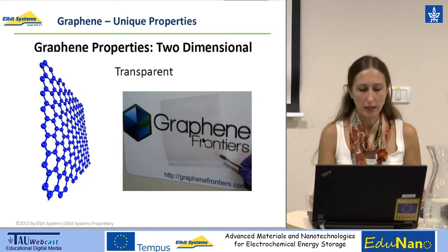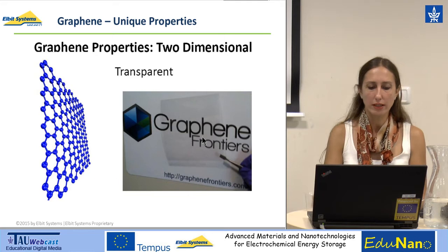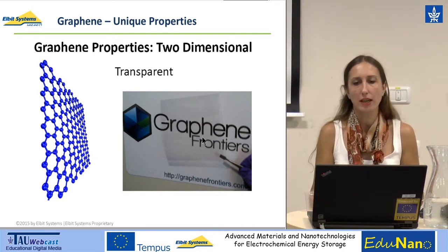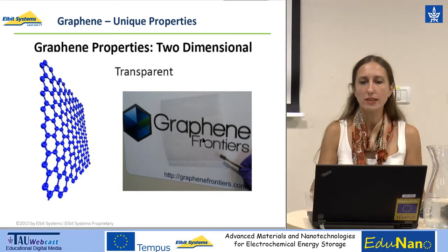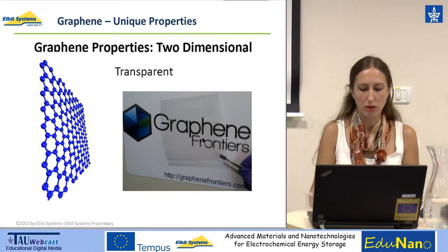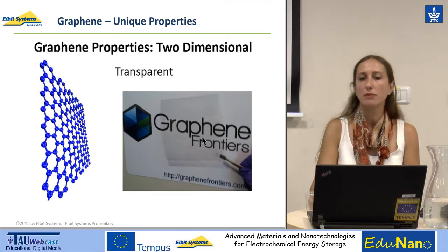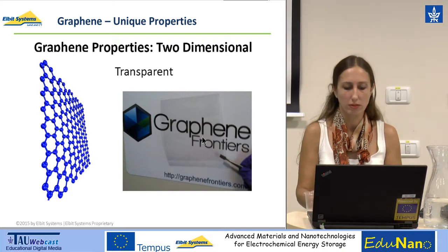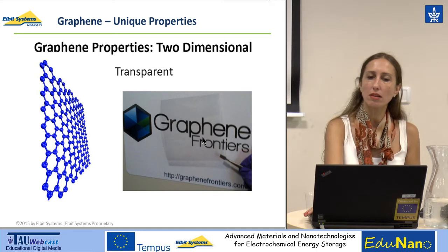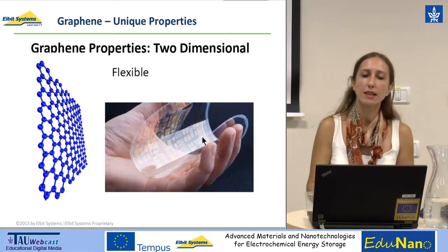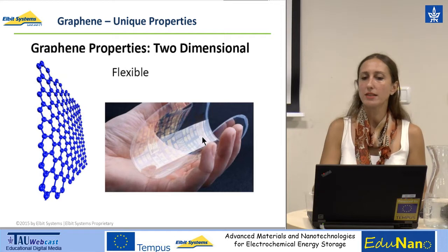When we talk about the optical properties of graphene, which are of great interest, they result from the strong pi-to-pi optical transitions in graphene and the large domain sizes, giving rise to novel nonlinear optical properties with high laser damage threshold energy. We are talking about broadband absorption coefficients ranging from the UV up to the near infrared spectra, and sub-picosecond up to microsecond responses by structural modifications. So graphene is not only a unique material for electronic applications, but also for optical applications.